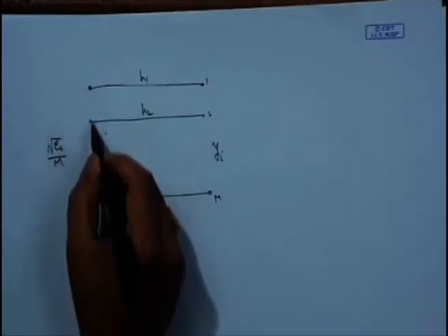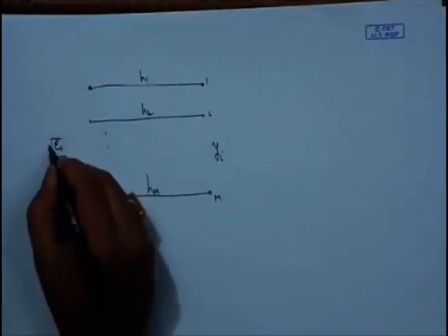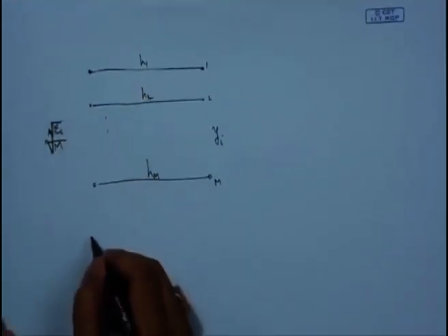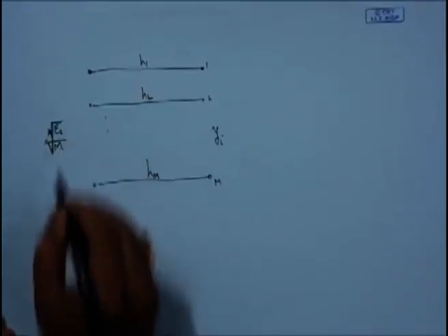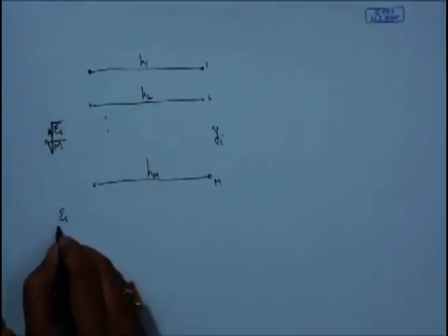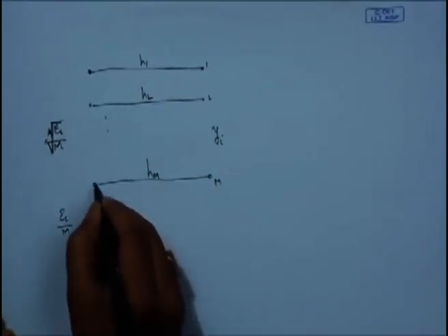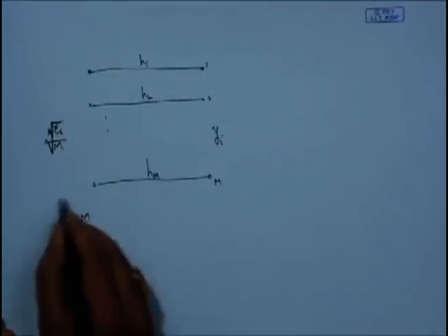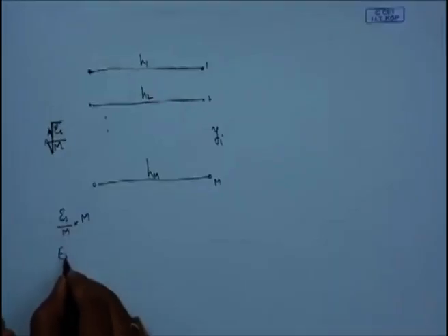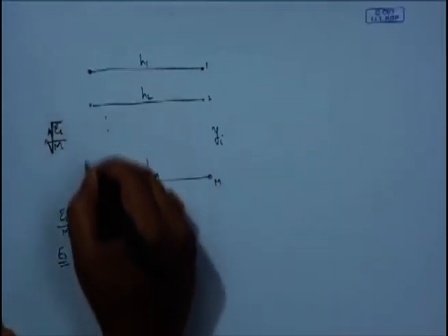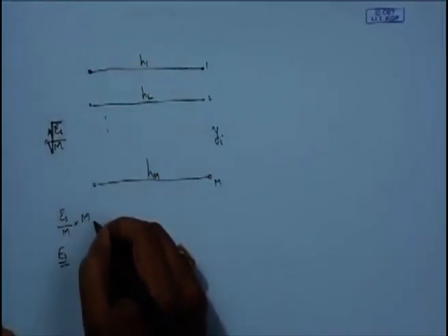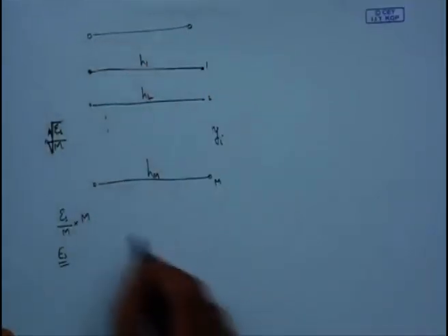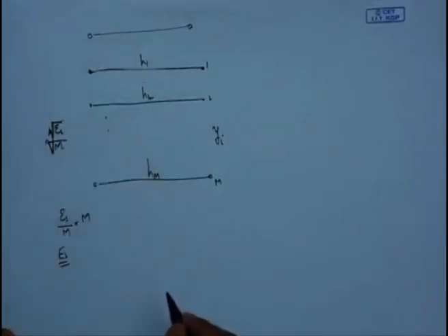So that means the power is done in such a way that the total power at the transmitter remains as Es. If you take the square of this, you're going to get Es upon M as the power of any one of the branches, multiplied by M number of branches. So basically the total power is Es. That's indicating that the total power of this system is not different from the case where I have a single input and a single output case. So this is a primary assumption which we will make.